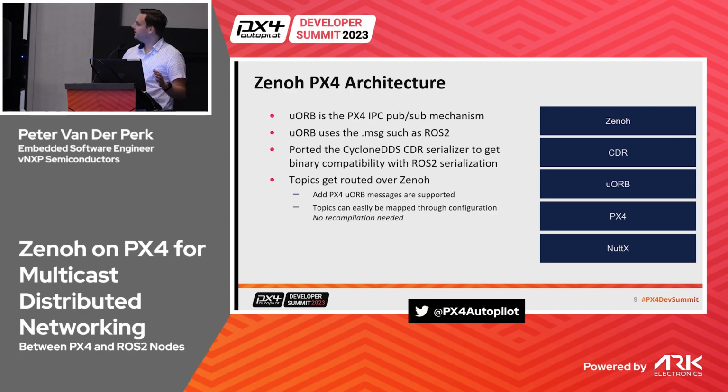And also something interesting about what we did in the Zenoh implementation now on PX4 is that we pretty much have implemented all messages. So if you have played around with the DDS XRCE mapping, you have to change your YAML file, make a custom mapping there, and you have to recompile. I've decided I don't want to do that anymore. I just want to have one binary. You can make a configuration file, and you can tell which topics go over where and which topics you want to subscribe to.